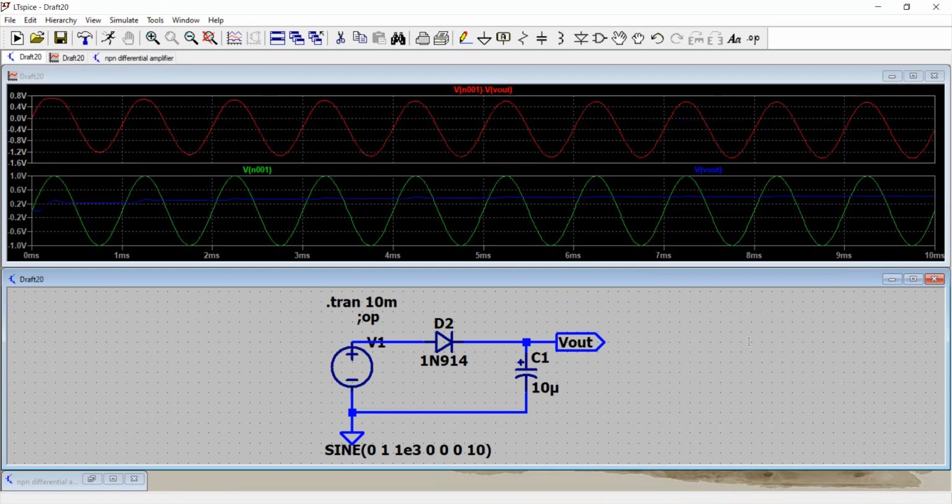Okay, now the next task is to cut the nets from here, select this diode and rotate it by Control R to reverse the direction, and then place the wires back in their position and see the behavior of this circuit. Obviously, now it is going to work in the negative half cycles. Run the simulation again and you see it's a negative peak tracker now. The waveform has changed and the forward voltage drop across the diode remains the same. But this is how you can build a simple peak detector using the diode.